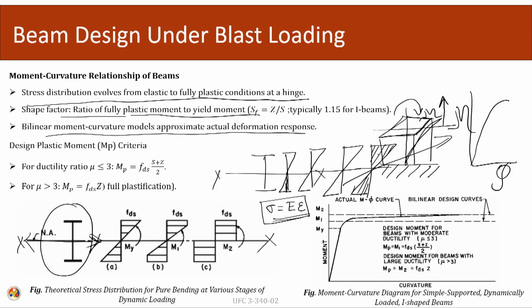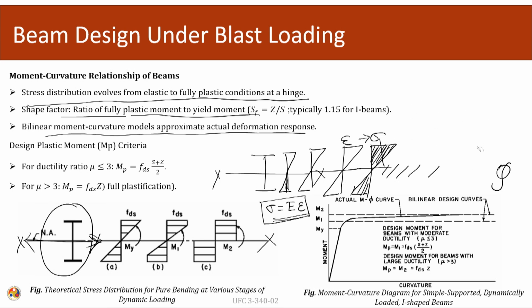Let us say this was the strain profile. So, from the strain profile we can get the stress profile. From the stress profile, if we integrate this distribution of the stress over the applied area, we will get the value of compressive and tensile forces.